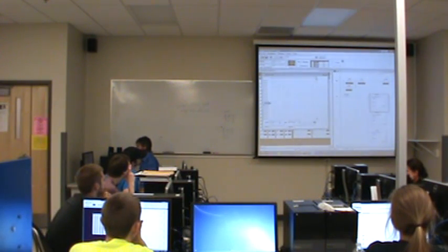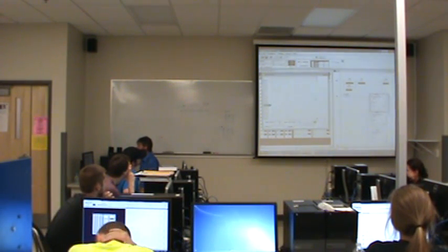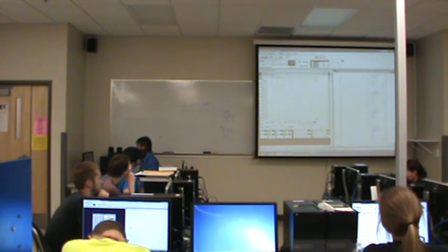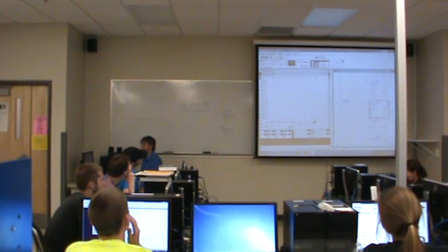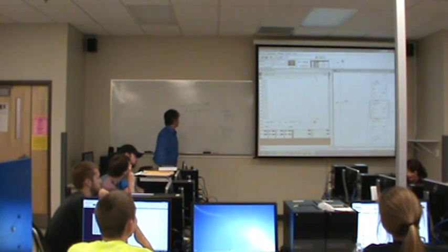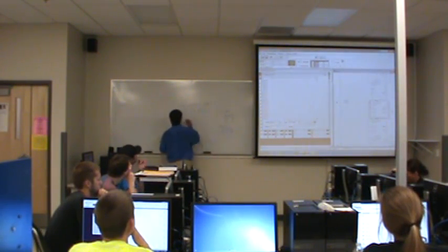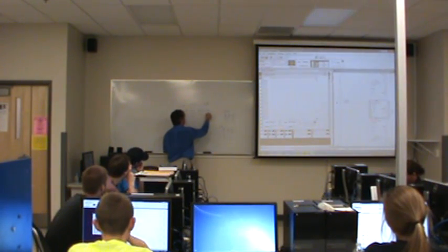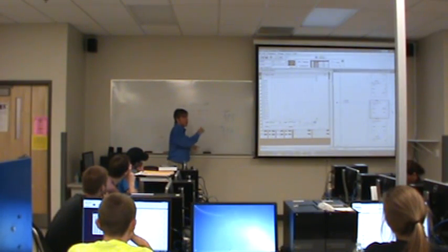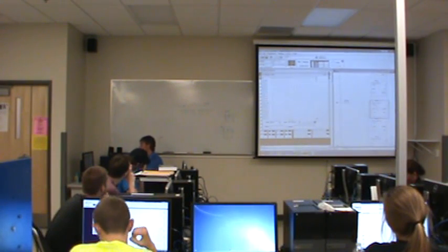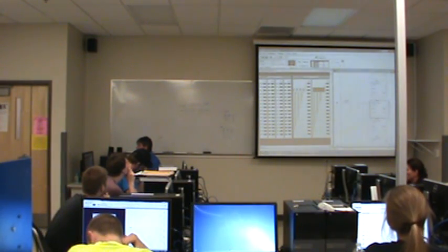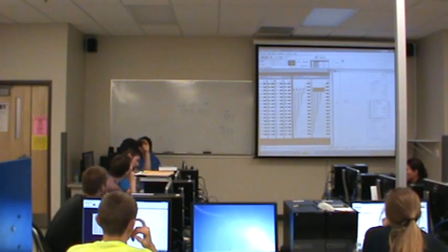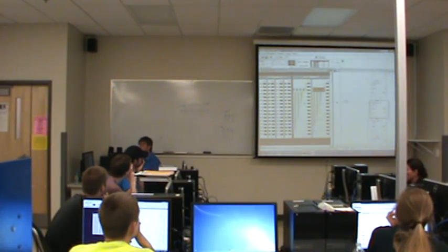Now, the input list is a little more complicated. Notice I wanted to work with the entire range of bits. And so instead of having a mask of 15, I use a mask of 65535. Now that mask looks like this. The mask is everything on. In other words, I'm going to deal with all of the bits in that word. And I have to, because the sequence that I wanted to see had to do with all of these. All these numbers together represent a pattern.